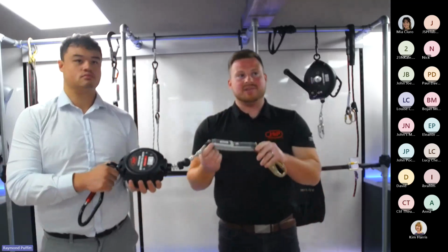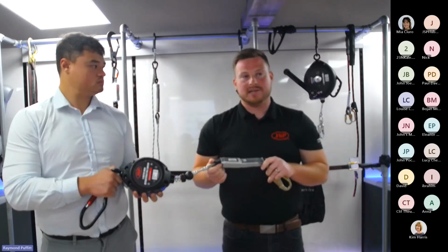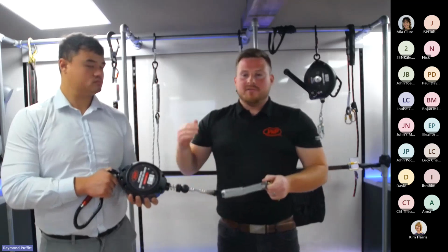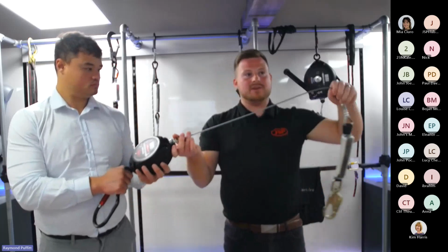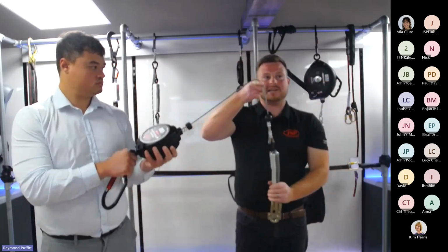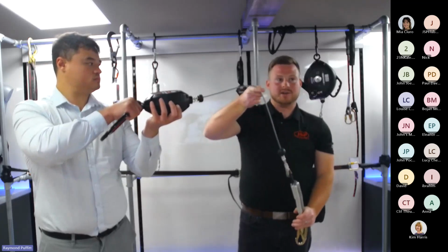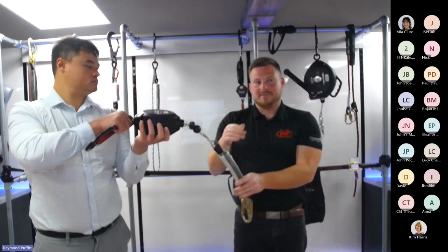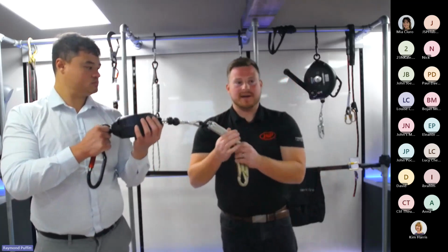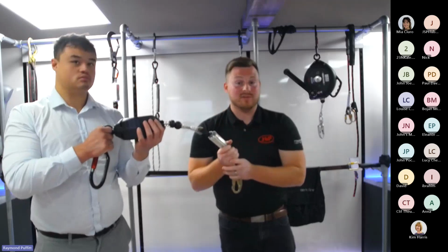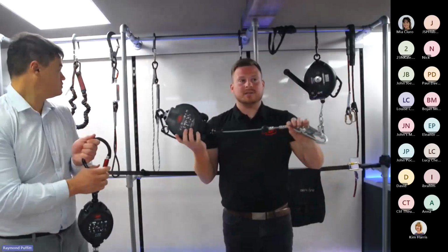And obviously, this is the key difference for it to be able to safely catch the user going over a sharp edge. So when we go over a sharp edge, obviously there's going to be a little bit of slippage with the blocks. The user's gone over a sharp edge, at a right angle, and it's going to catch you. Chances are it's going to slip a bit before it catches you. Once it then catches you, because it's slipped a little bit, there's going to be a lot more force in that fall, which is why we have the shock absorbing pack, which will then deploy as it does for a 4S lanyard. Standard block doesn't have that.